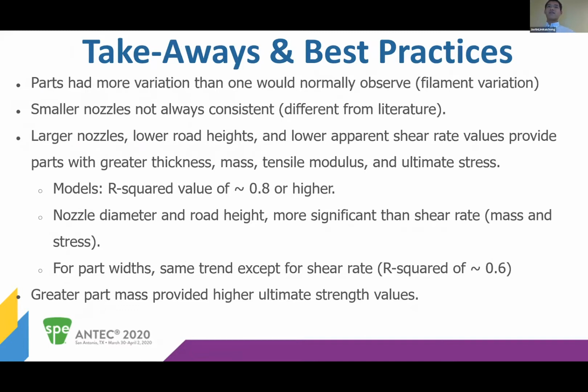Something that we also noticed and realized after all of this was that smaller nozzles will give you better resolution, but there is some trade-off with your part strength, and there is some value in printing with larger nozzles, because I know that a lot of people only try one nozzle, which is the 0.4 that comes with your typical desktop 3D printer. So there is some value in going higher or lower depending on what you want.